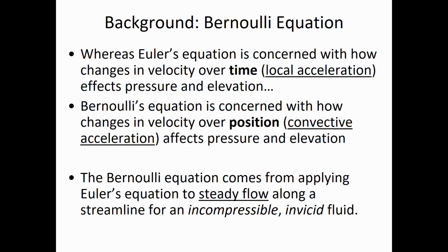Now, along a streamline, so what would the streamlines look like? Well, the flow that's over here is going to move there. Our streamlines are basically an indication of the relative direction of the velocity at any location in the field. So we've got our streamlines that are just indicating the direction, and these non-parallel streamlines mean, oh, there's some acceleration happening there, there's a change in velocity.